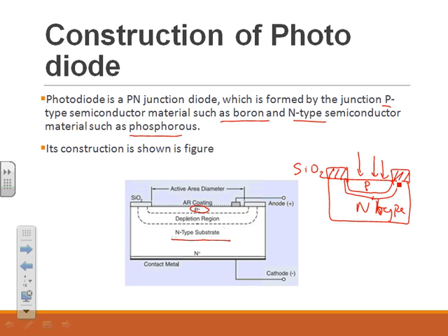By theory, we would take a p-type material and an n-type material, join these two, and they form a depletion layer. Actually, we cannot form a p-n junction like this. So the p-n junction is formed by the diffusion process. Here there is an n-type substrate, and to this n-type substrate a p-type impurity is diffused, like this.